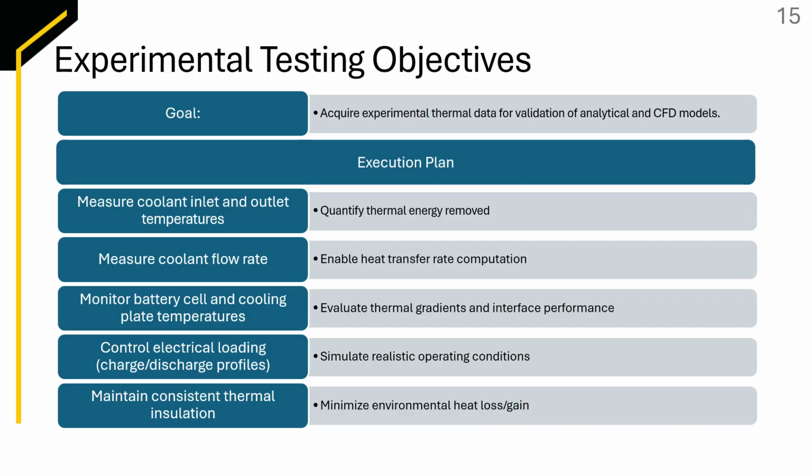For our experimental testing objective, we have one main goal: to acquire experimental thermal data for validation of analytical and CFD models. We're going to use the execution plan of measuring coolant inlet and outlet temperatures. We're going to measure coolant flow rate. We're going to monitor the battery cell and cooling plate temperatures. We're going to control the electrical loading, which is the charge and discharge profiles, and we're going to maintain constant thermal insulation.